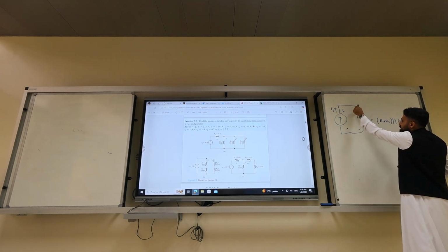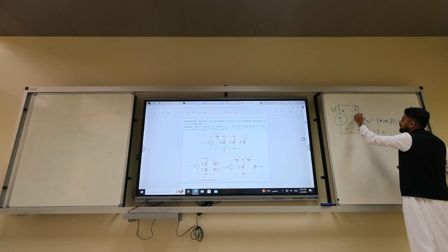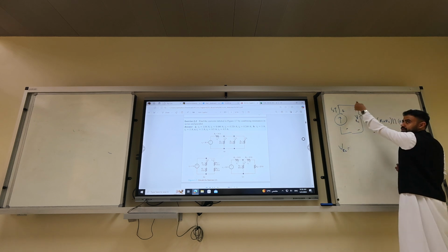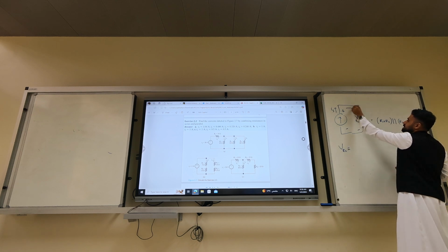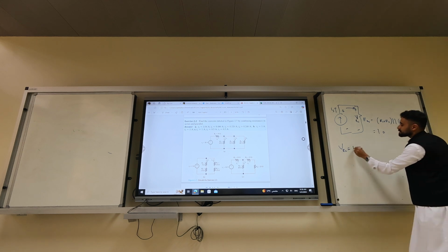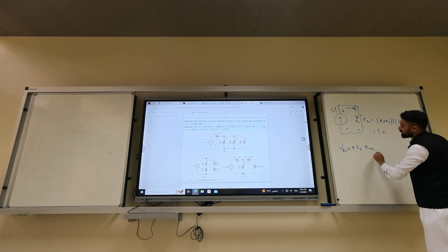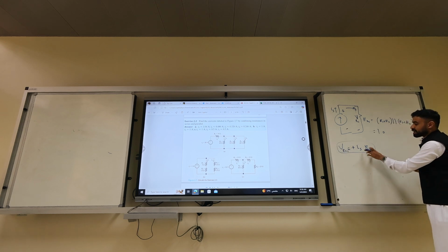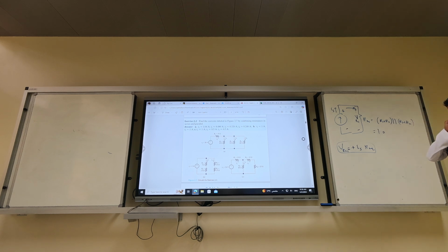I want the voltage here, plus or minus VR equivalent. So VR equivalent equal plus or minus? No, the current enters from the plus. Option 1. Plus IS times R equivalent. So I calculate the VR equivalent. Now, after I calculate VR equivalent, no, it's also for Ohm's law.